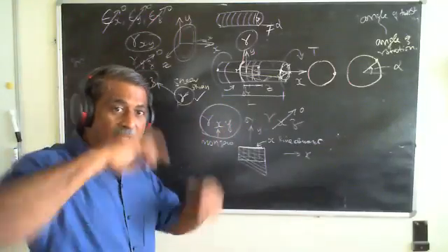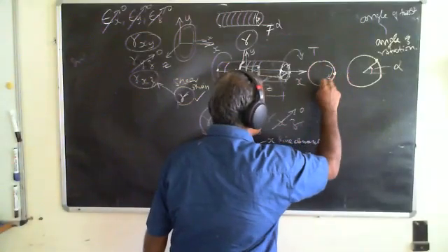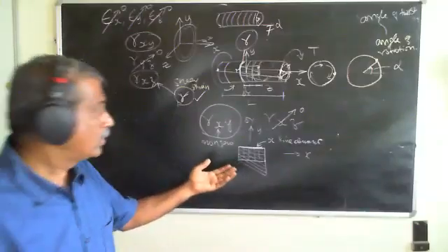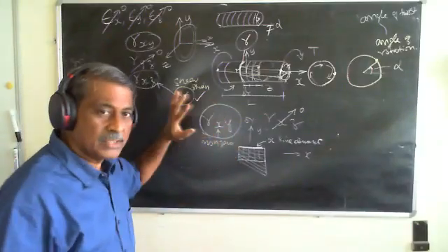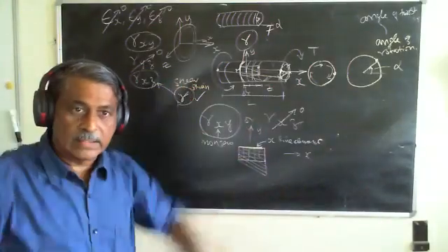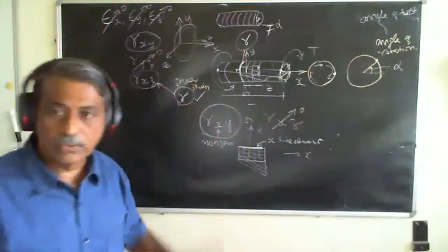But if I take the polar coordinates, then whatever is in this direction is the one that we are talking about as a non-zero gamma. So there is only one shear strain present because of the torque applied to a thin tube. So far, okay?